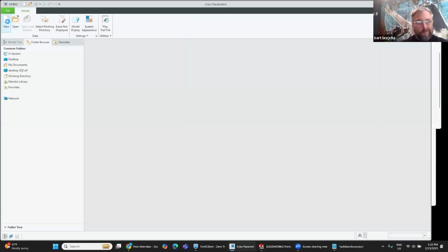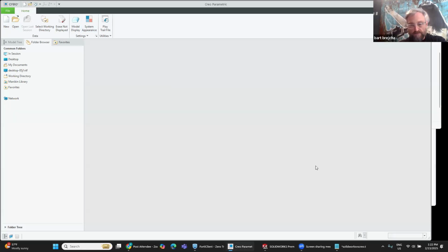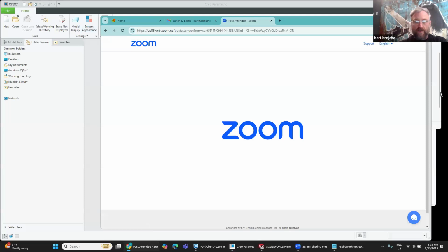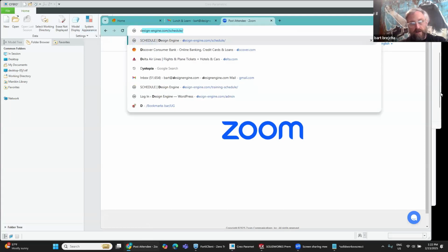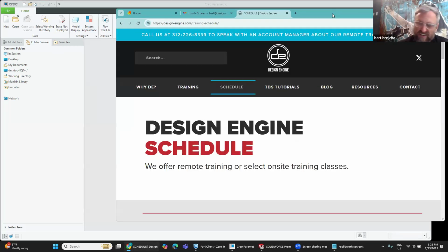I teach a 2-day Import Data Doctor class, and I don't know how much experience you guys have playing with Import Data Doctor, but if something doesn't come in, it can be kind of frustrating. Import Data Doctor gives me absolute and unbridled control to delete surfaces and rebuild them all inside of Import Data Doctor, and you can collapse anything that you build outside of Data Doctor inside of the geometry.